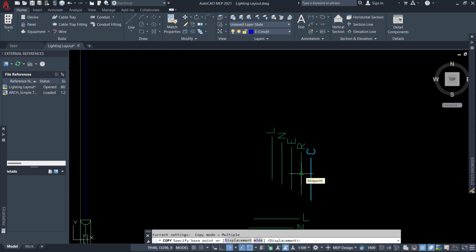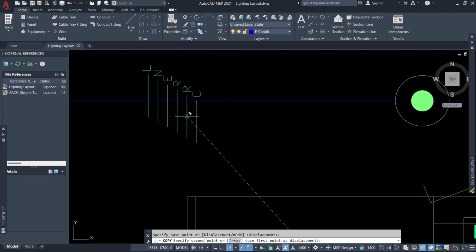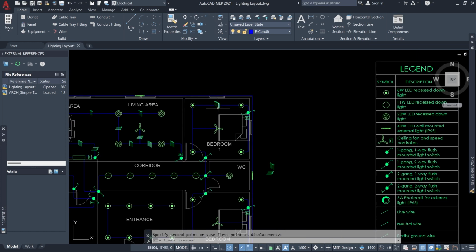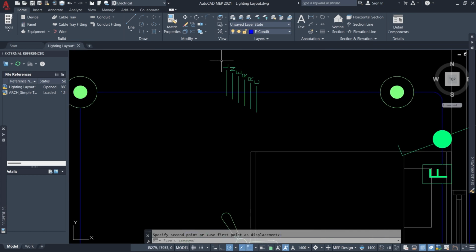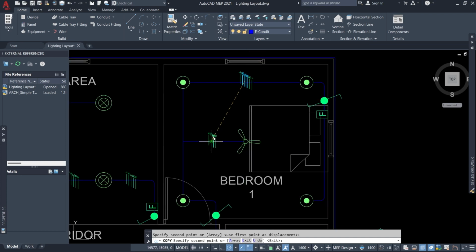What that basically means is that you need a control wire. Okay. You need a control wire. This control basically is the communication between these 2 switches. Okay, and at this point we can only talk about a neutral, earth, and a return for the fan, this branch.